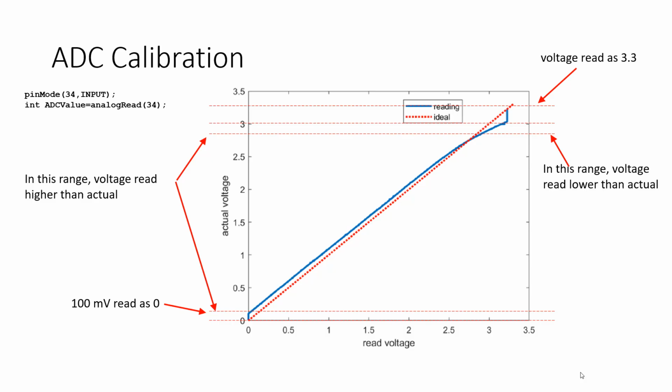So then I think it was Alex who figured out that these power supplies can be controlled by the ESP32. They can be slaved to the ESP32. In other words, you can write software on the ESP32 that takes control of the power supplies, and that gives the software a ground truth reference, because if it sets the power supply to, say, 2.5 volts, it knows that the read voltage is 2.5, well, 2.5 times 43/10, since there's that conversion factor too.